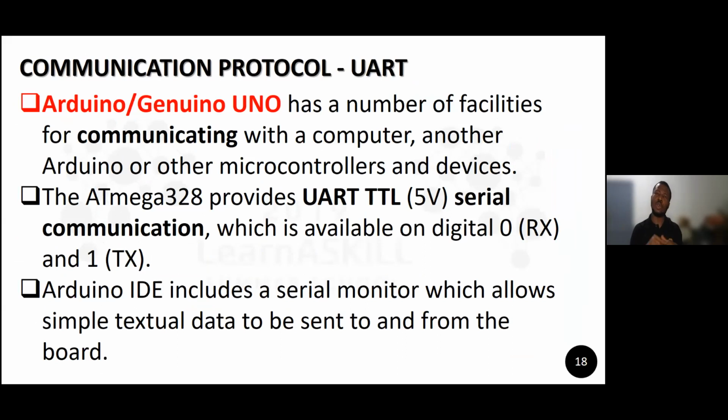When we talk about a communication protocol, it's a means by which Arduino communicates with other devices. Basically, we have what we call the UART or USART. USART stands for Universal Synchronous Asynchronous Receiver Transmitter. The UART happens to be a subsection of the USART.